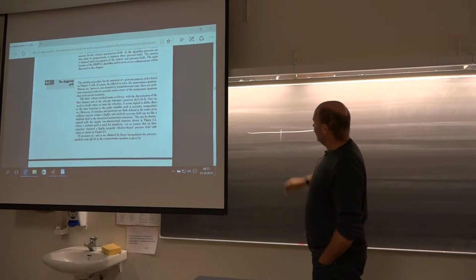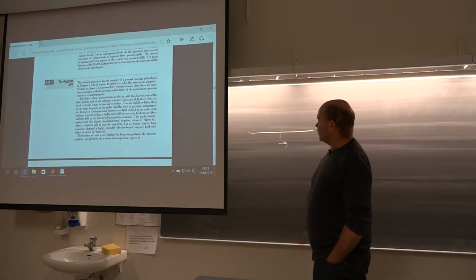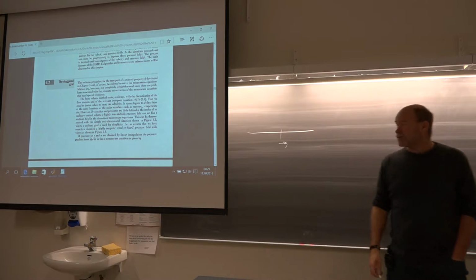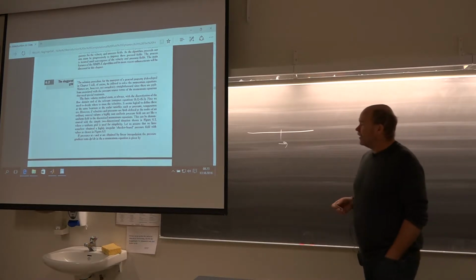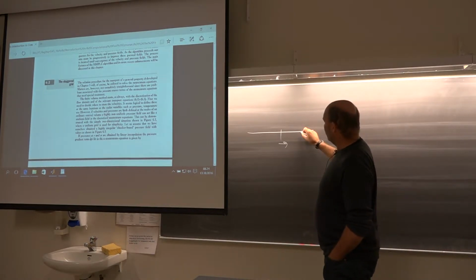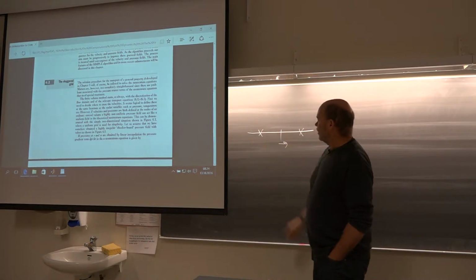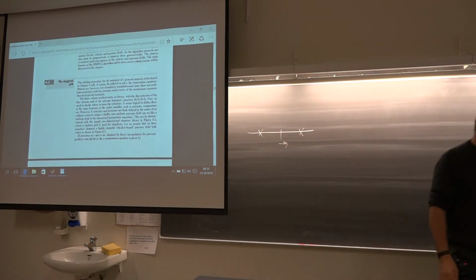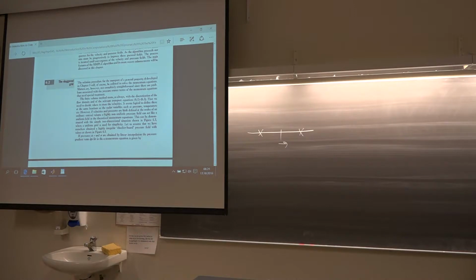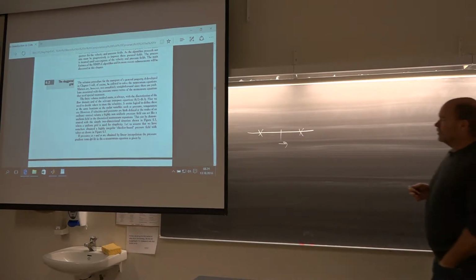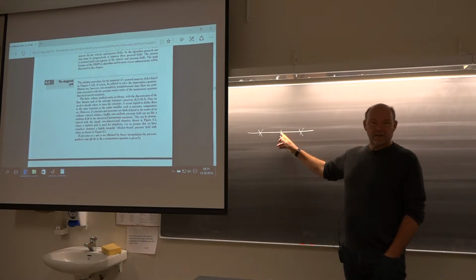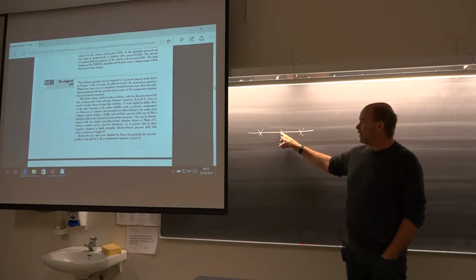when you are seeking the solution for the velocity at one point in space, then in the Navier-Stokes you are going to need a pressure difference. So typically you use central space discretizing, and you use a pressure on each side of the velocity. But the pressure where you are standing doesn't enter into your discrete equation.